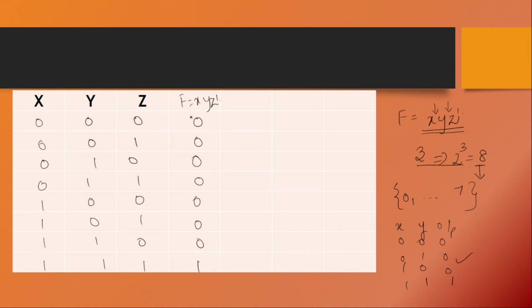So this is how you form the truth table from an expression. First of all, you identify how many input variables are there for that expression. Then you identify the combinations possible. Then you list down the combinations in a sequential order. And finally, in the output column, you analyze the expression with the help of AND, OR, NOT, whatever gates are present there. With the help of the basic truth table of those logical operations, we can wind up the final answer here.